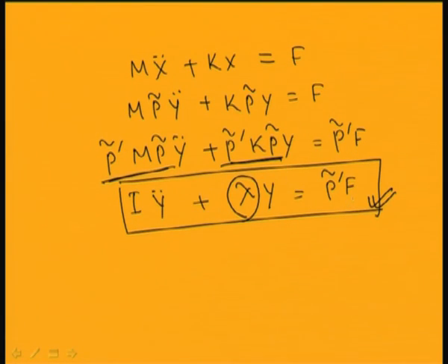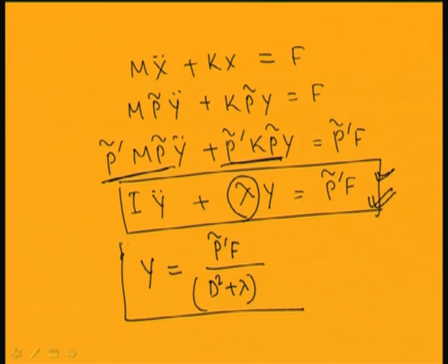In this case, you just have to multiply this weighted modal matrix P transpose with this F, and you can get the solution from this equation. The solution can be written as y equal to, if you are finding the particular integral, P weighted modal matrix transpose F divided by D squared plus lambda. So, by taking different functions f, you can find this y of the system.